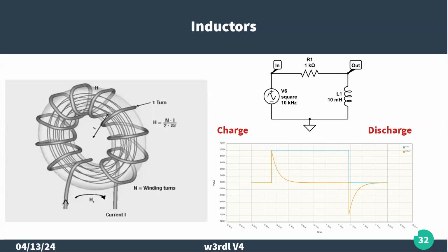About that. And it's because as it goes through, that copper pipe looks like a one-turn coil that's shorted together. So that magnetic field is creating current in the copper pipe, which is creating an opposing magnetic field, which is what slows it down.